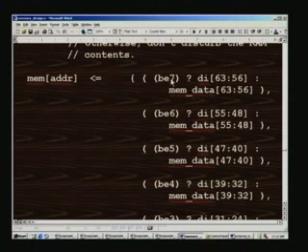If this is not satisfied, especially for a read operation, this won't be satisfied, then also this will be executed. So we have to take enough care for that. What we do is simply write itself back to it. So this and this are precisely the same. You write the very same data back to the same byte. That means you don't disturb the contents because it is in read mode.